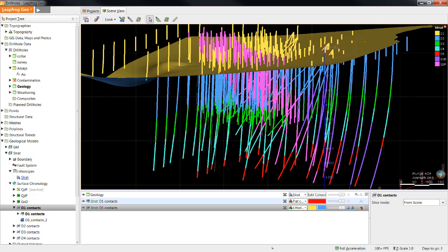you should use them. A first-pass surface created in a geological model using drill holes is the result of connecting contact points in a simple isotropic environment, as we see here. Given how quickly Leapfrog can generate these first-pass surfaces, this is a great place to start, but not always a good place to stop.